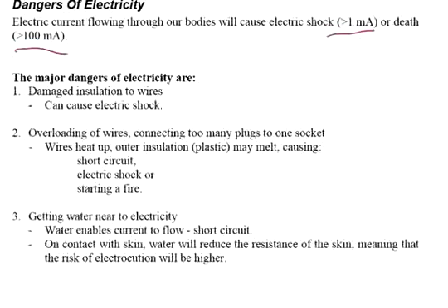The major dangers of electricity are damaged insulation of wire, and overloading of wire, which can be caused by connecting too many plugs in one socket. The wire will heat up, the insulation plastic may melt, causing short circuit, electric shock, and can start a fire. And number 3, getting water near the electricity. Water enables the current to flow or can cause short circuit. In contact with the skin, water will reduce the resistance of the skin, meaning that the risk of electrocution will be higher. Don't worry about that part.